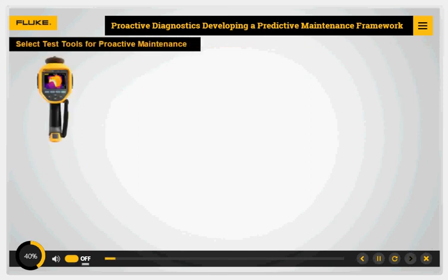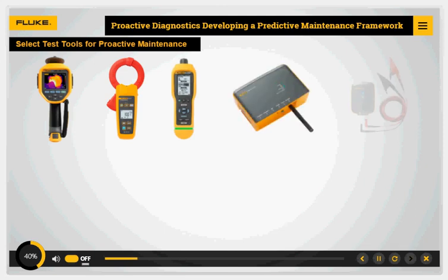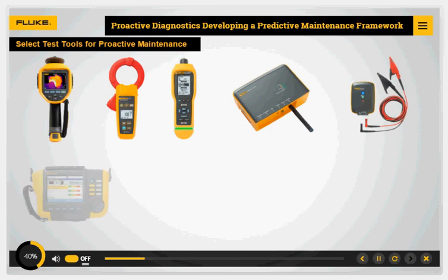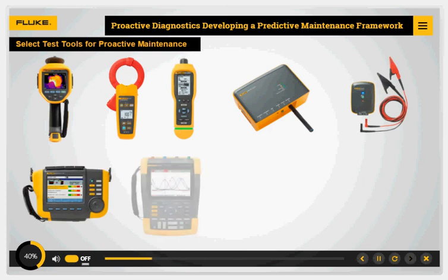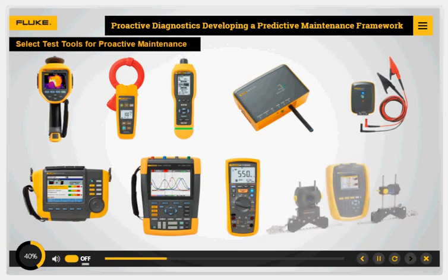Proactive maintenance teams use test tools to collect measurements that are key indicators of asset health, such as operating temperature and vibration levels. In order to spot a change in system performance, you need to take the same kind of measurement at the same point on the system time after time, comparing the new measurement against the previous reading or against a known good sample or a go/no-go threshold.